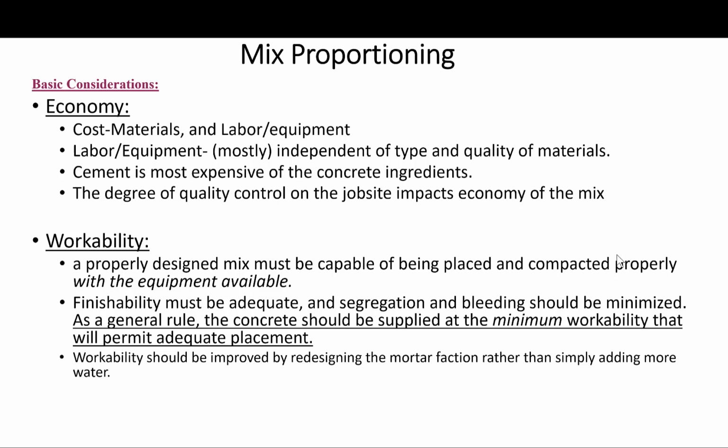Clearly, as we have been talking, a properly designed mix must be capable of being placed and compacted properly with the equipment available. Also, finishability must be adequate, and segregation and bleeding should be minimized. We discussed the workability and its related properties in the previous module.